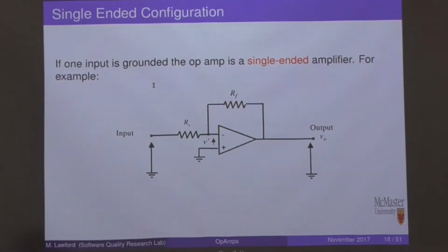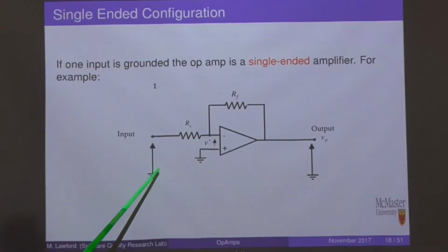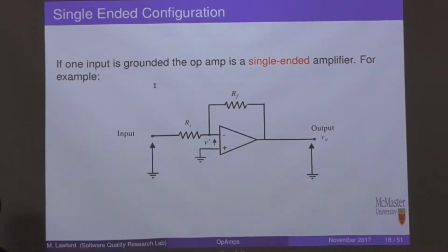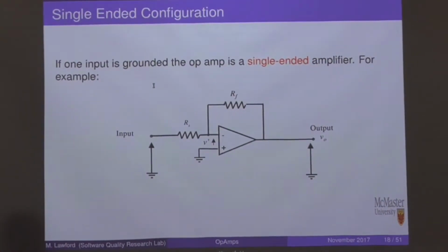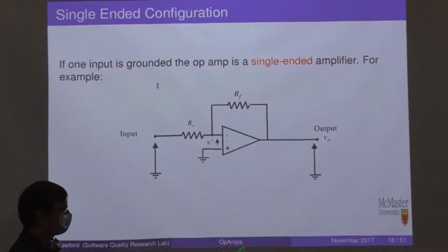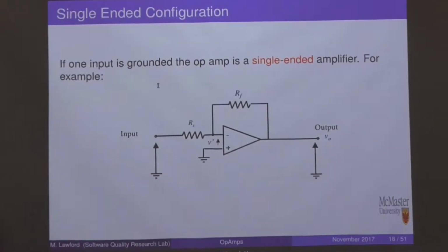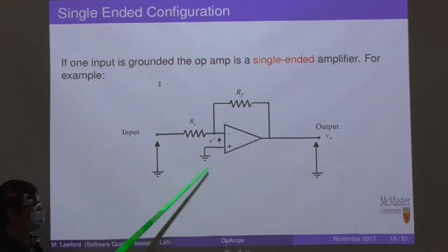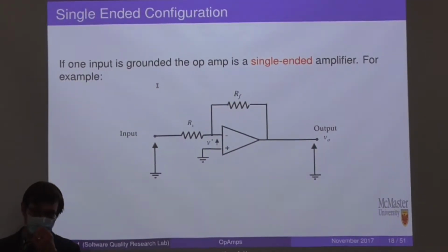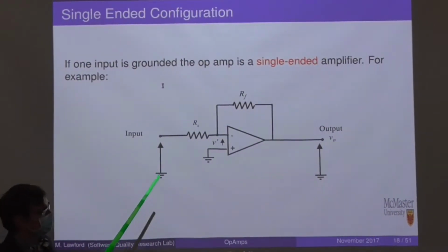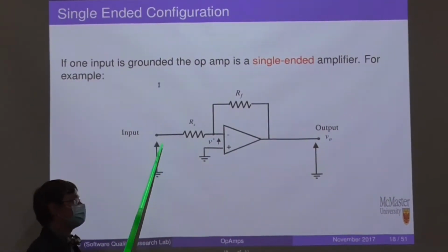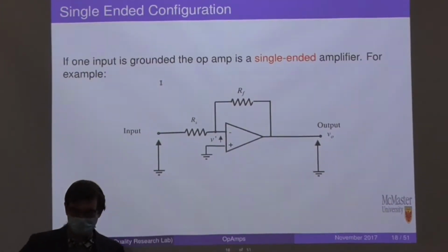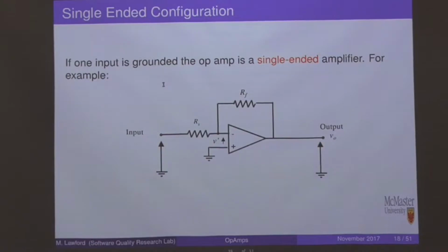So, an interesting effect. A lot of people think that ground is just ground, right? It absorbs all of the electrical energy and you don't have to think about it. However, it turns out that ground is not as easy and uncomplicated as it first seems. We're going to have a few slides on this coming up, but essentially, you can have frequency signals which pass through the ground wire in a circuit and fluctuate and throw things off and cause noise and interference.